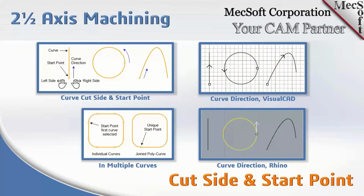Now you're going to want to understand how the tool is going to cut, how it's going to start cutting, and what side of your control geometry is going to be cut. You have different options in the cut parameters tabs of the 2.5 axis operation types to tell right side, left side, inside, outside, etc.